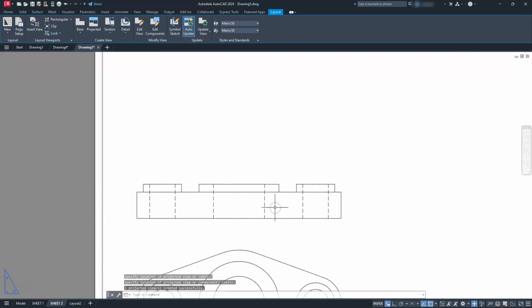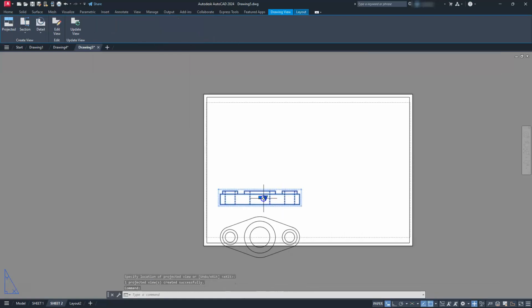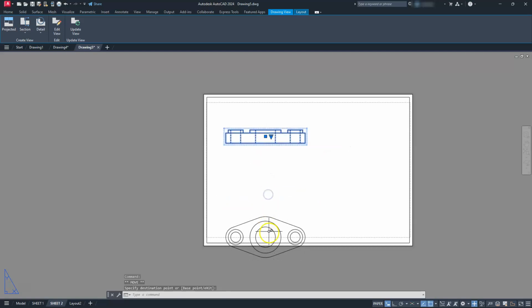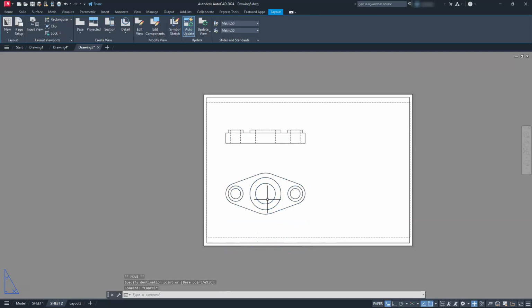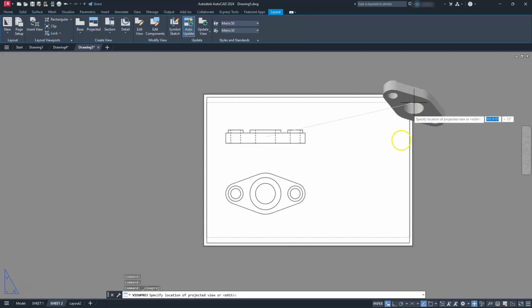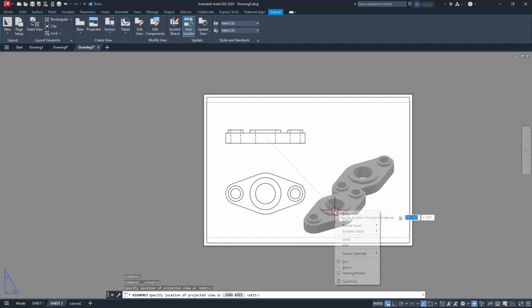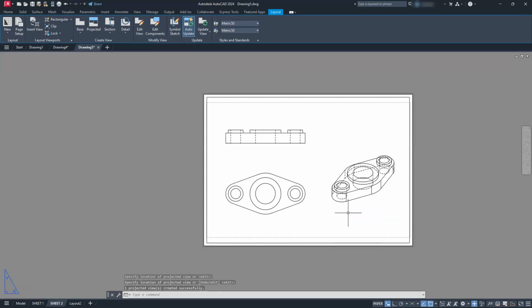All right. So that's the one good thing about if you set it up correctly. Every now and then it'll get me because I'm so used to doing everything in third angle projection, but this is a first angle projection object that I am creating. Let's go ahead and see what an isometric looks like. So I'll go back here, I'll select this view, Project, and then I'll go up here in the corner, and I'll go ahead and click this way. I just did a right click and hit Enter. Okay.